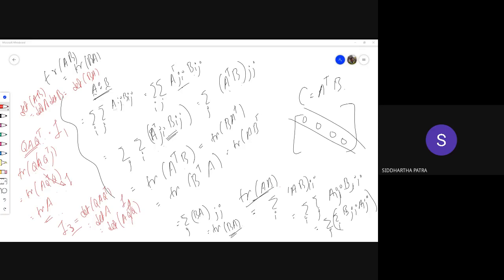In mechanics, a lot of times the strain energy like formulation pops up where you take the inner product of stress with strain. And just the way we discussed, the inner product of two matrices is essentially multiplication of each term in the stress tensor with the corresponding term in the strain tensor, and then adding them up. So there are 9 terms that have to be added.